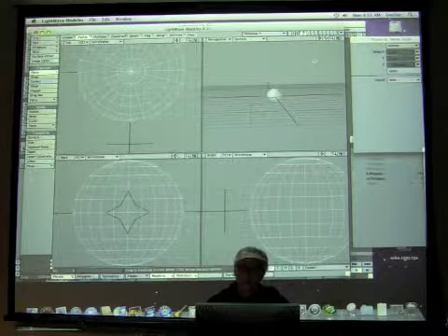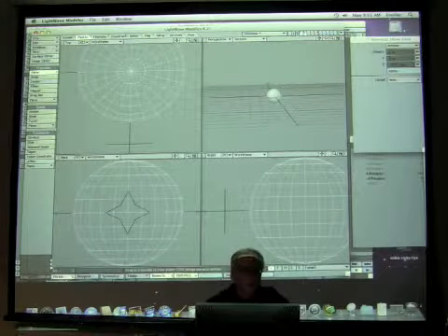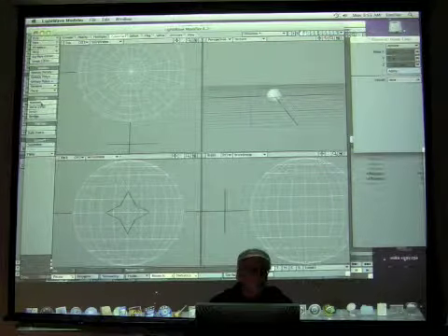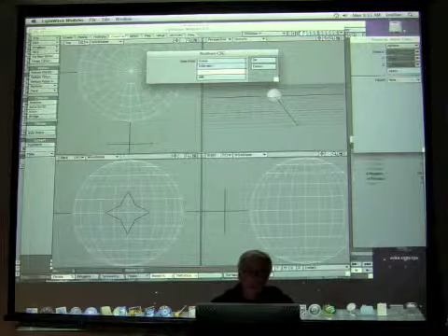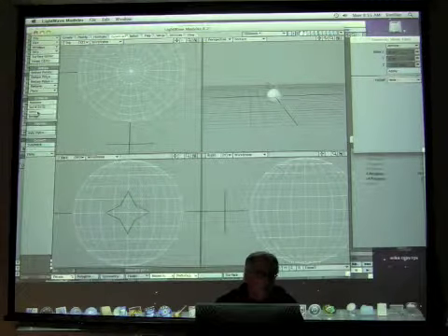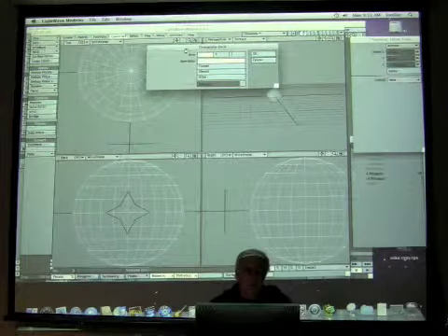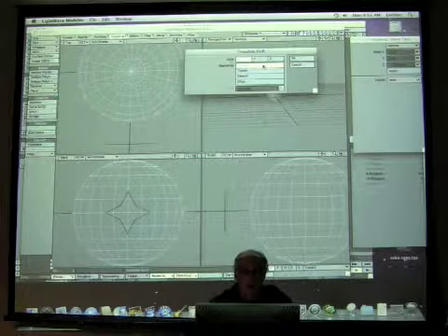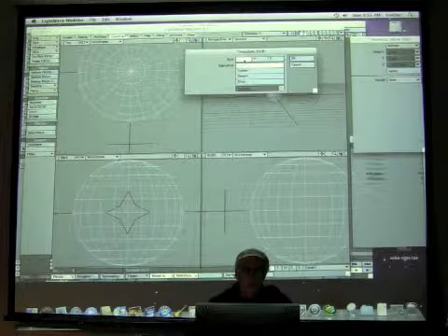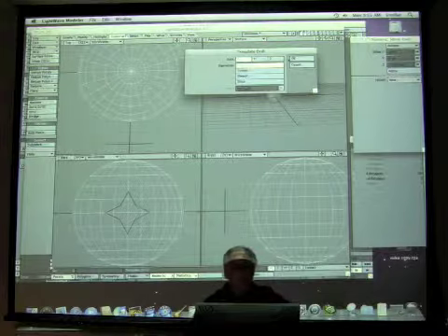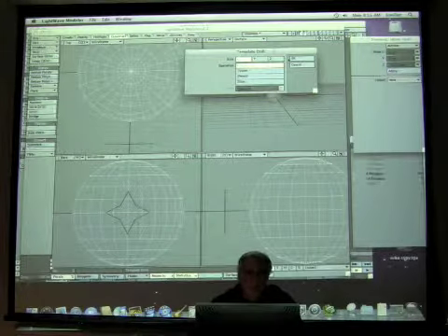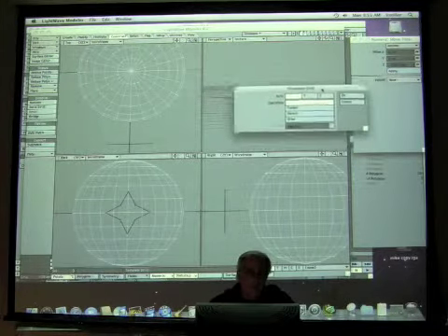And what I want to happen could be one of 3 things. When I go to construct and I select Boolean, actually that's not what I want. I want drill. Drill is a Boolean function. But with drill, you can only drill along the X, Y, or Z axis. Which axis am I going to use?